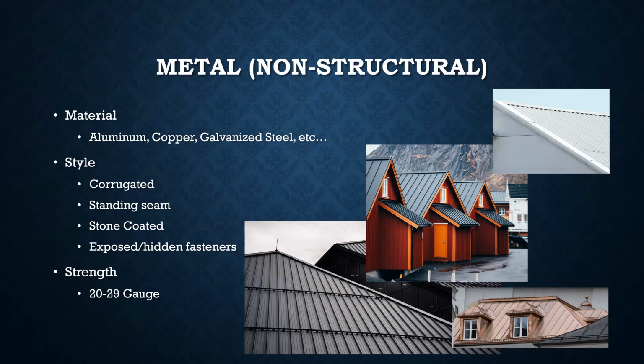I heard a story from a builder where he strictly uses 22 gauge or something on the stronger side, and all the other guys in the neighborhood had done it with a cheaper gauge, and a big hailstorm came through, and everybody's roofs had a bunch of dings in them, except for this one guy that he built, which had the tougher gauge. So it can be worth it if you want to pay for the longevity and the toughness.